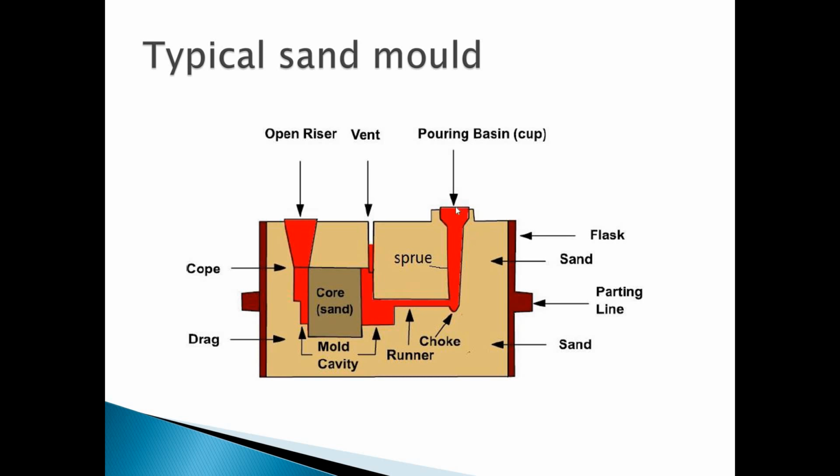So how do we check whether the poured metal has reached the mold cavity? By observing the open riser having liquid metal.